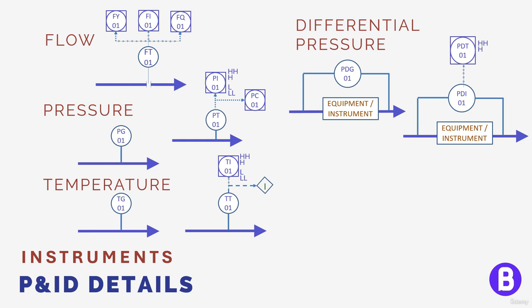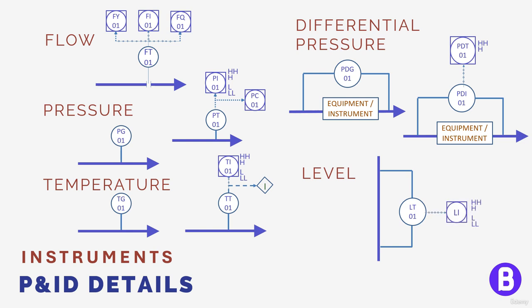We can also monitor the level in a vessel or in a tank, or send the level reading to the control room, same as all other parameters, or use them in a control action or a shutdown action based on a very high or very low level value.